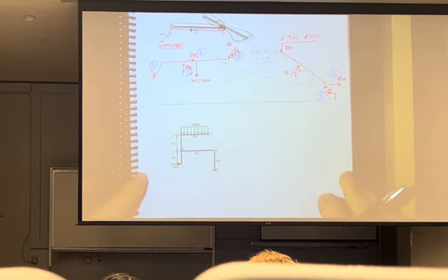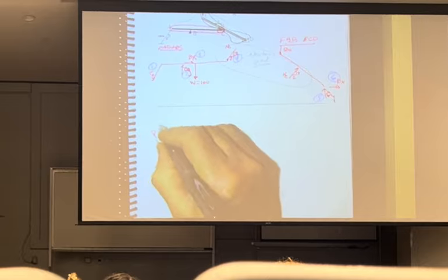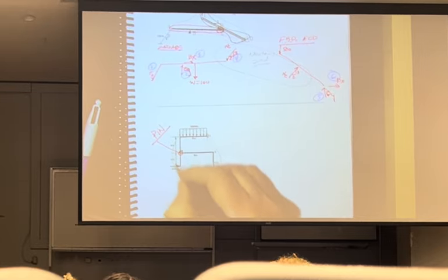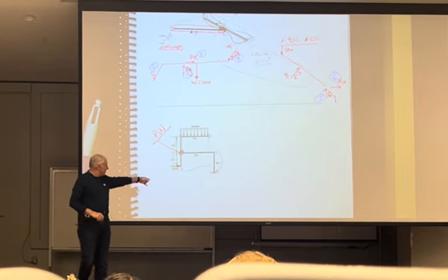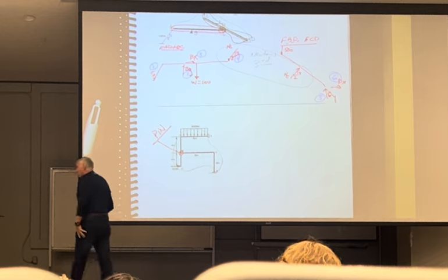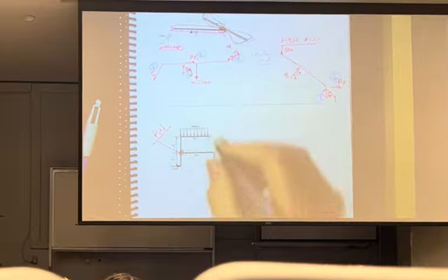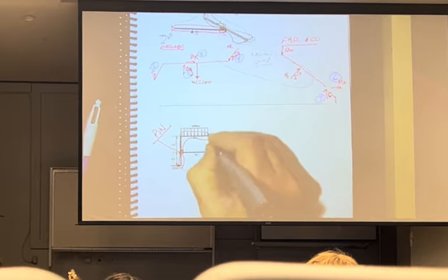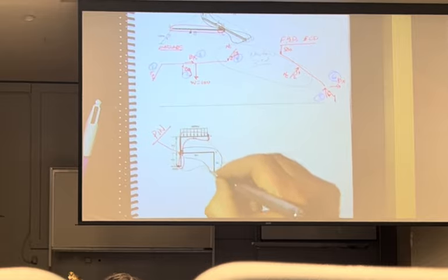Questions? All right, moving down to the bottom one. There's a pin here. Notice, if I draw a free body diagram of this, that's 2 unknowns, go through here, 2 more unknowns and back. That gives me 4 unknowns: 2 at E from the pin, 2 at A from the pin. Not a good look. I can't solve all that. So instead, I'm going to cut through here, cut through here, cut through this, and back. And then I'm going to cut through here, cut through the pin, and back.